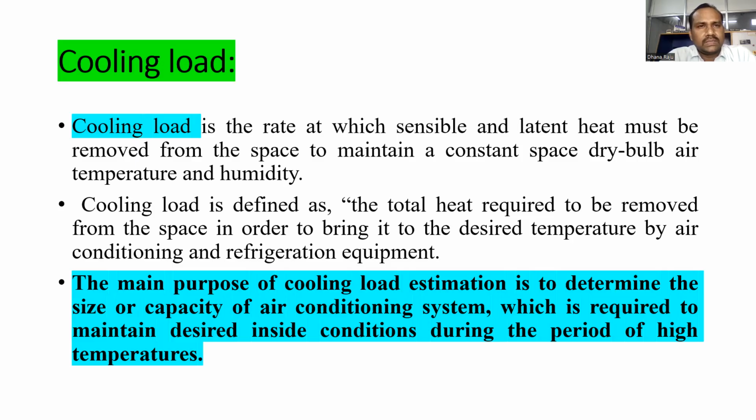Actually, cooling load is the total heat removed from the space so that the space is maintained at specified conditions which provide comfort for the people. If we are able to remove the same amount of heat that is present in the space, then the space is maintained at the required conditions in terms of temperature and humidity. That is done by knowing the cooling load.